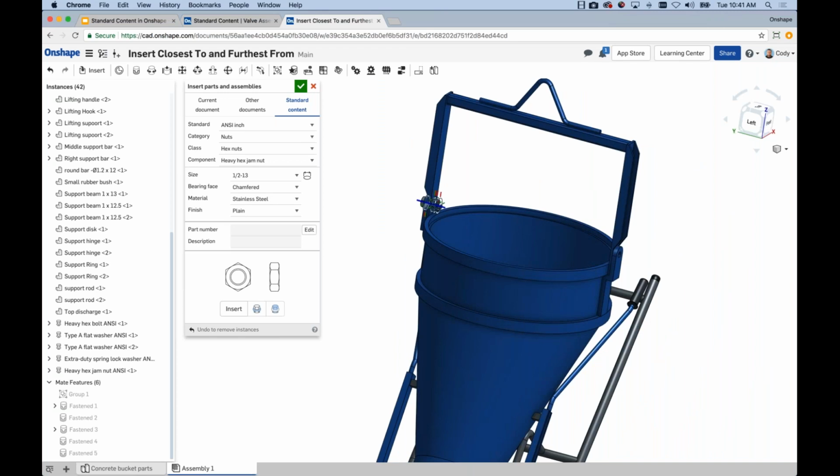I'd say use the rollback feature so you only delete one and reinsert one. Yes, you can. You can undo too. A good point. You can undo if you've just recently done it. You can go back to the history if you've done that, but it's fairly fast to reinsert as well.